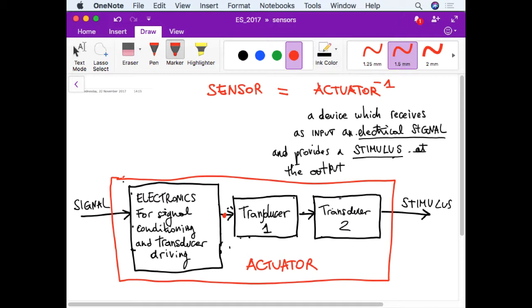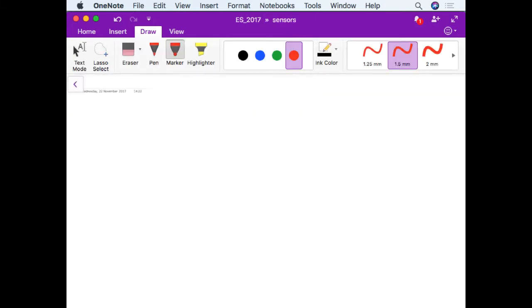then there's some amplification, and also some proper encoding to be done. Okay. In the case of sensor, one of the main roles of the electronics is to actually extract the signal from the noise and provide a proper amplification in order to increase the signal to noise ratio. In the case of actuators, the problem is of course different, because the signal is typically pretty good. Okay. So the typical situation in which sensors are used is a so-called data acquisition system.